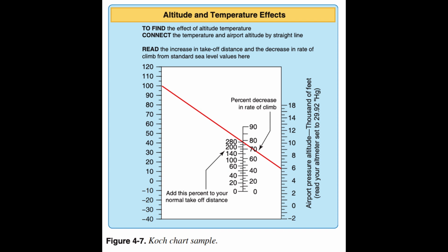Lift. Lift always acts in a direction perpendicular to the relative wind and to the lateral axis of the aircraft. The fact that lift is referenced to the wing, not to the Earth's surface, is the source of many errors in learning flight control. Lift is not always up. Its direction relative to the Earth's surface changes as the pilot maneuvers the aircraft.